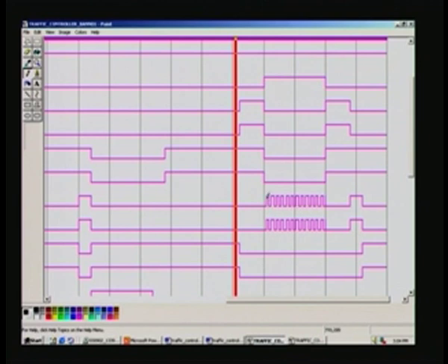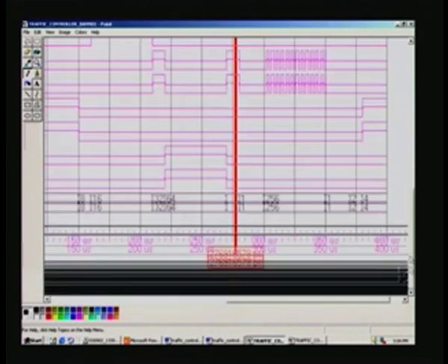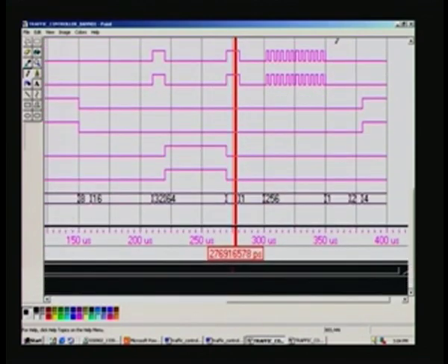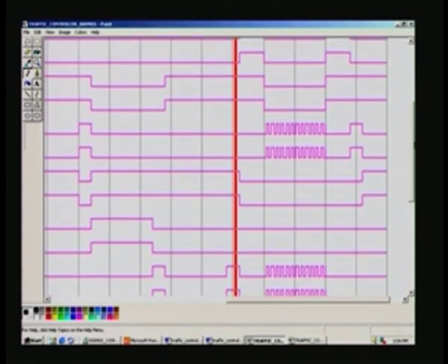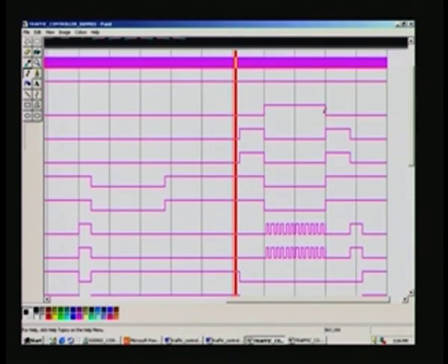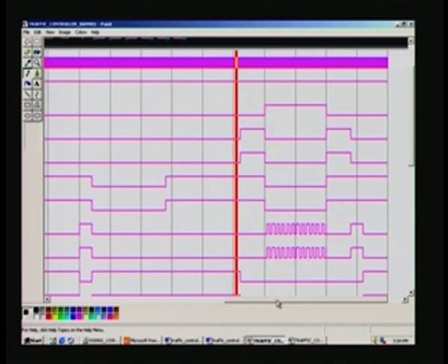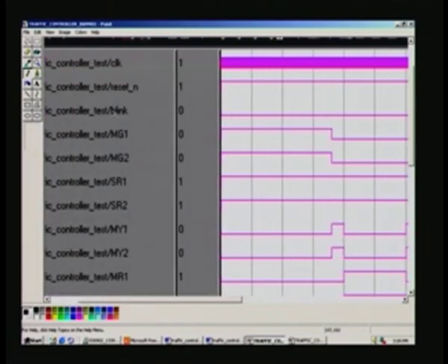So, be on the lookout for such design flaws. In traffic controller, it may not matter much. Anyway, for control applications like programmable logic controller, etc., that is a very vital thing. Not a single unwanted spike must be there. And this clarifies the whole thing is working in back annotation, and then it goes to state 1 after this one once the blink is removed, and blink you can see here corresponding to that. Blink is also high here, this is the blink here, and it is withdrawn there. So, you can see right there as blink. So, this proves that the whole thing is working, our design is working.